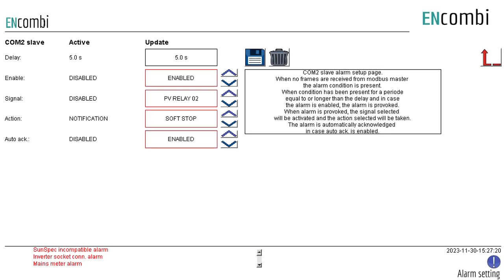And further, ECPv2 can serve as a slave when using more than one ECPv2 controller. In this case, one ECPv2 will serve as the superior controller and the second one as the slave. Here you can set an alarm if the slave controller is not receiving any data from the superior controller, and the alarm signal can also be used to activate relays.